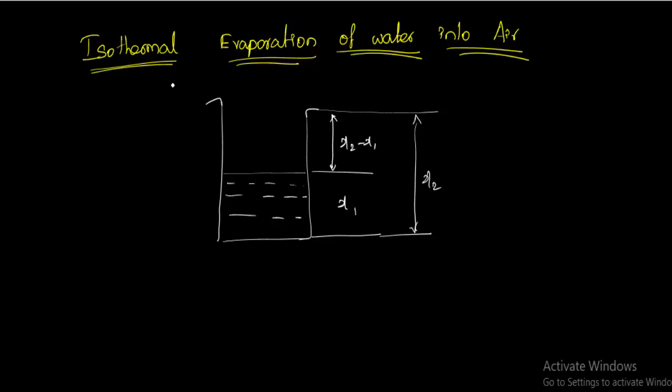Okay, here the air is flowing in this direction. Because of the air flow movement, the water inside the cup will start to evaporate and mix with the air. So here there will be water vapor, right? So water here is converted into water vapor and it is stored here. By means of the air flowing in this direction, the water vapor is taken into the atmosphere, right? So here it is MA, the water vapor diffusion rate, molar flux.